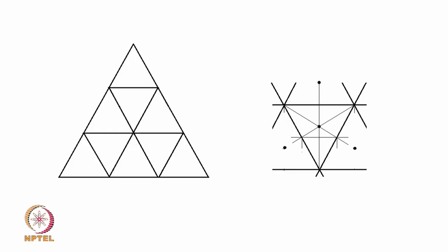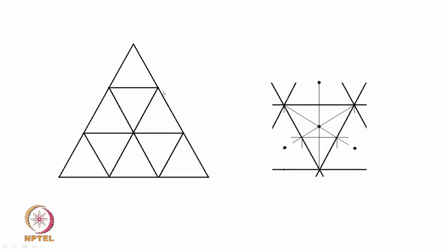So, that means that the first step of finding the solution, which is determining the nodes at which we would like to deliver the velocity, is done in the following way. That is, we triangulate the domain, we split it into triangular cells. In this particular case, we have the luxury of making it into equilateral triangles, which is not necessarily the case in general.